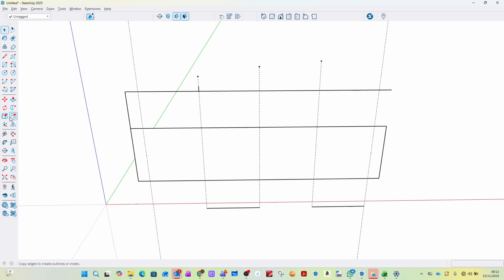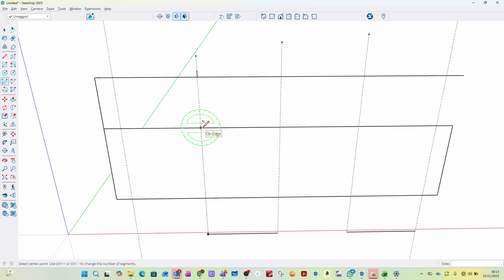My roof, I'm going to use the arc tool. We use this one here. There are several arc tools we can use. I'm going to put my cursor down to this point down here. It's automatically snapped onto the green axis, which is perfect. However, I can force it onto the red, the blue, or the green axis. I'm going to go up to the top of there and bring it down. Now, on this occasion, I would like it at 45 degrees. I could eyeball it.